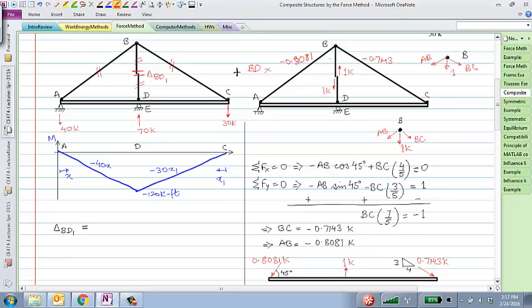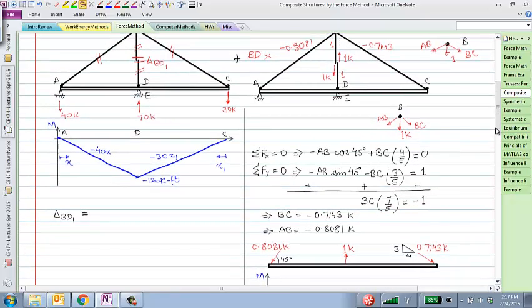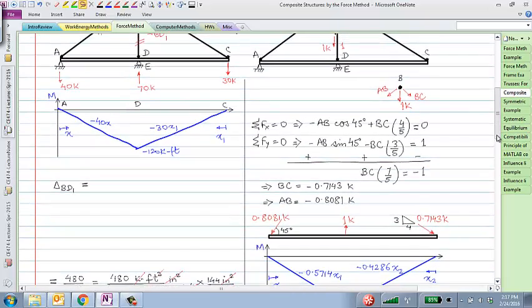The two halves of BD are just in 1 and 1 tension, right? So I know the forces in all of these truss members. Now if I look at the beam out here, ADC, that beam is under these types of forces. One pulling up, because this member is in tension in the amount of 1. There is this force pointing down in compression, and there is this force pointing to the right in compression.